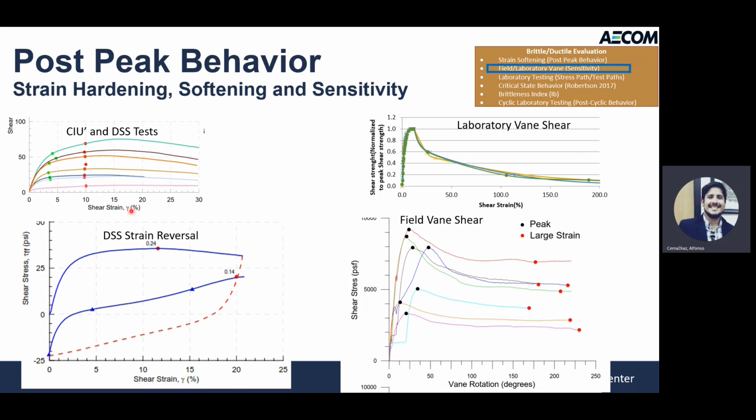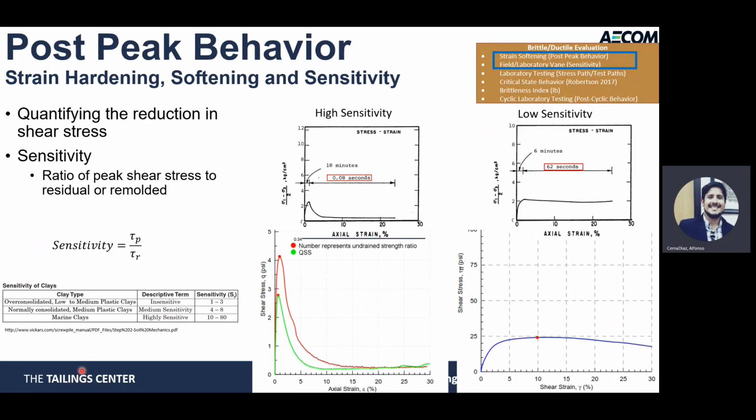Some other testing is done with a monotonic direct simple shear test, in which you take different cycles and there are strain control tests, and you can see the drop in the maximum peak stresses. And that also gives you an idea of the sensitivity. So this is not something new. In fact, it has been studied for the last 60 years. I'm showing here a couple of examples from Gonzalo Castro. If you recall, Gonzalo was Dr. Casagrande's student at Harvard. So the top two plots show sandy types of materials, and the bottom is what I show in terms of tailings. So the same behavior. For example, for a highly sensitive liquefiable sandy material, you will see that initially under stress control triaxial testing, you increase your shear stresses.